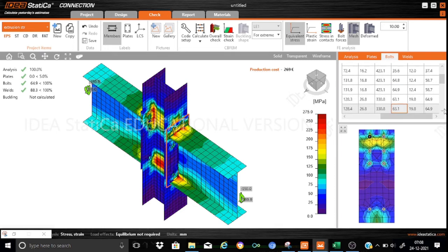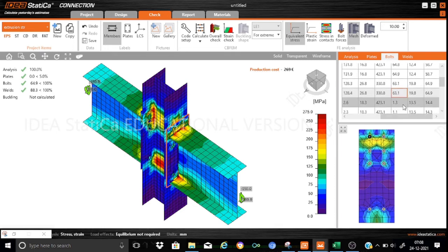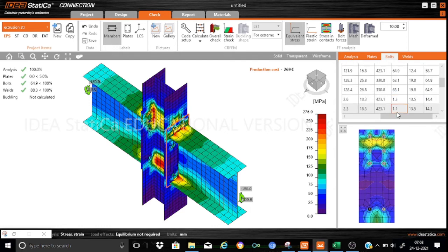And going to, so look here. If you see the bolts that are located at the bottom, you find that they are subjected to almost zero tensile forces. So this could also explain the reason why we normally use such bolts for taking the shear loads, and the top bolts indirectly taking the tension. So that is readily substantiated through this analysis.